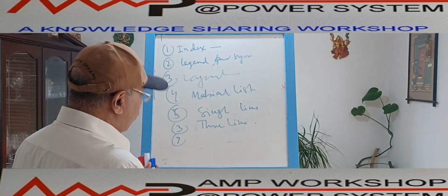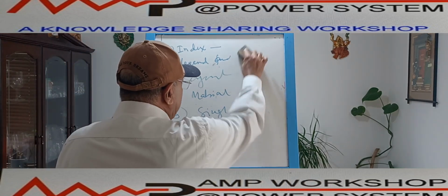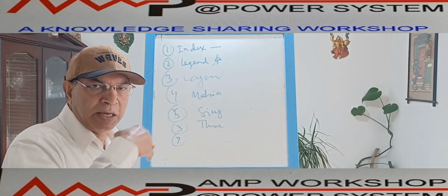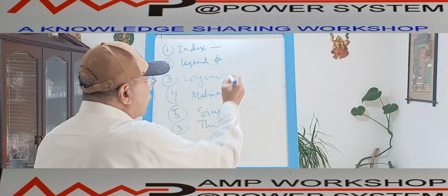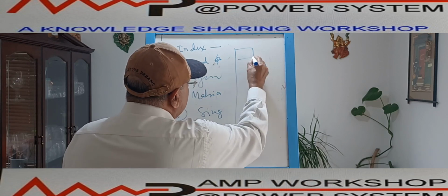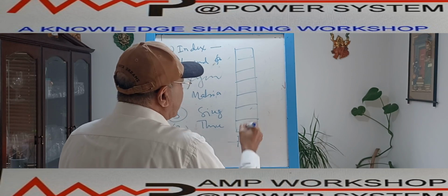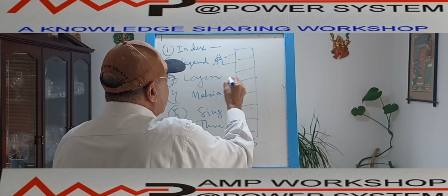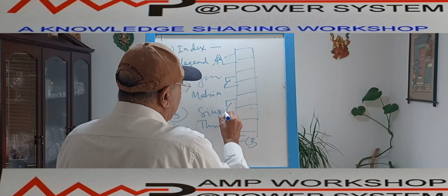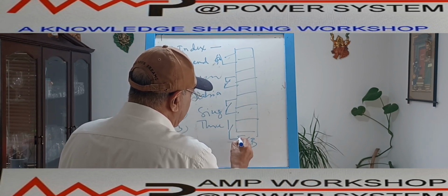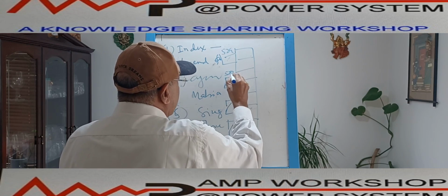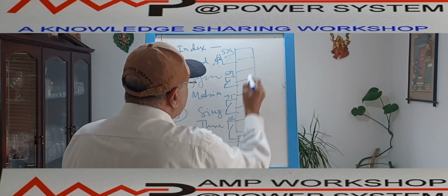Normally, when the switchgear schematic is finally completed, the switchgear is connected to the various outside field devices and control equipment. So there will be a field terminal block, we call this the field control terminal block. In this terminal block, all the auxiliary contacts or signals are connected. Suppose there is a breaker NO contact, this breaker NC contact is connected over here. Suppose here is a 95 relay, the 95 relay contact is connected over here. Suppose the lockout relay contact is connected over here. So here it will be, suppose 52A, 52B, it is 95, it is 86. So it will be written over here.